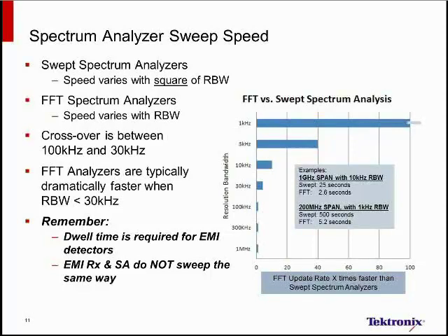EMI receivers and spectrum analyzers do not sweep the same way. We are a swept-tuned signal analyzer for your average spec A. We're a stepped-tuned receiver. And the EMI receiver can actually define the number of steps that it will take between the low frequency and the high frequency in a specific range. This is significantly different than a regular spectrum analyzer, where all we can control is the actual sweep speed itself.